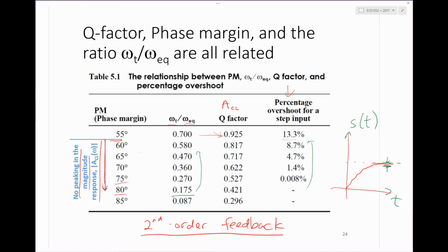But if we put feedback around that thing, in order to keep it stable, what we're seeing now is we have to back off from that bandwidth by a factor of 4, a factor of 5, just to make sure that the amplifier doesn't have crazy settling time and things like that. Okay? So you'll sometimes hear it said that feedback comes with this kind of speed penalty. That's what it means. Just in order to keep the thing stable, you have to back off a bit from the poles and compensate things to give you between 60 and 85 degrees of phase margin.